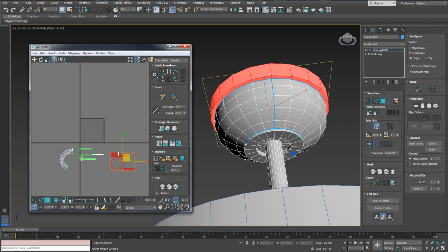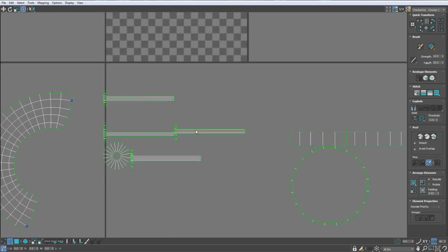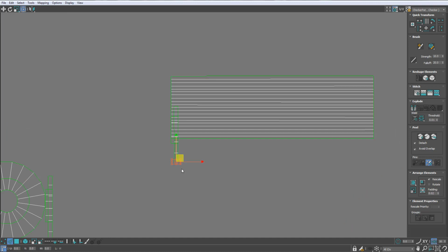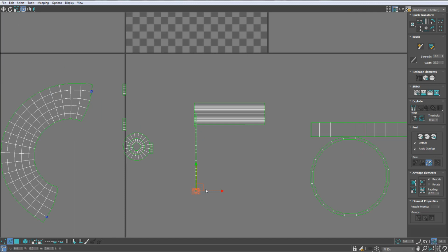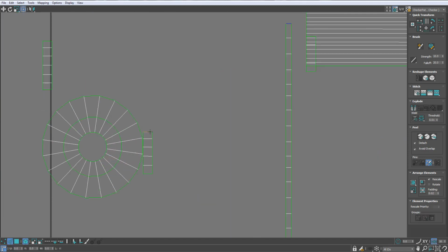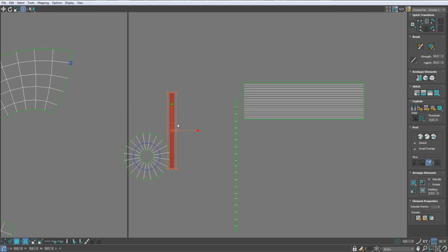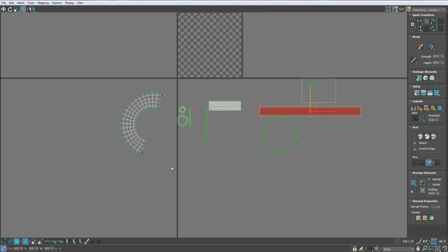So, for the most part, as I said before, it is all about organizing our UV shells and trying to stitch all the pieces together. You can do this by right clicking and selecting stitch selected, or just use the shortcut Shift S from the keyboard, which is what I use in order to save time and, of course, to save your energy through the process.